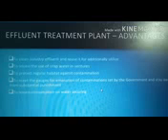So, the design. The design of an ETP depends upon the quality and quantity of wastewater released from the different industries and the land availability. If the availability of land in your industry is less, then a common effluent treatment plant is preferred over an individual effluent treatment plant.